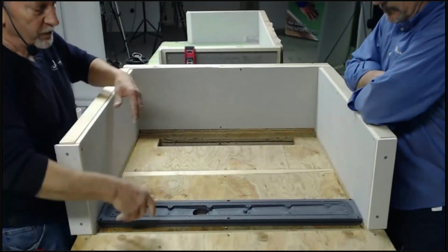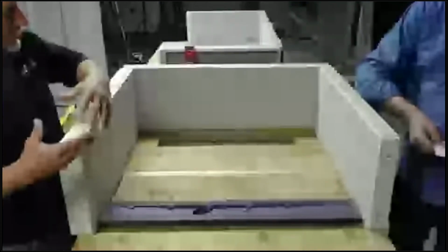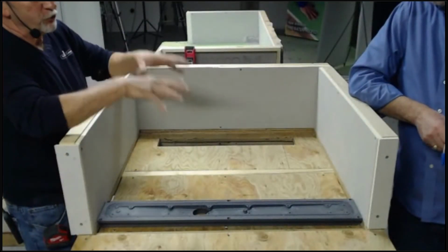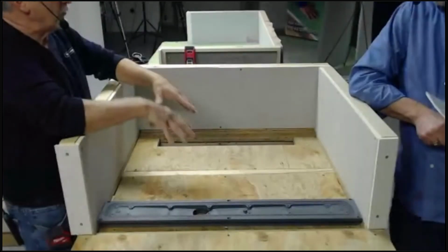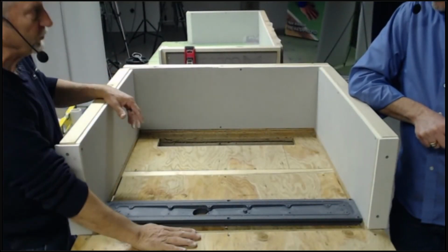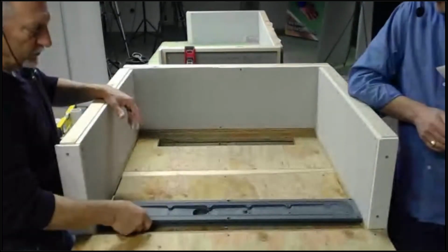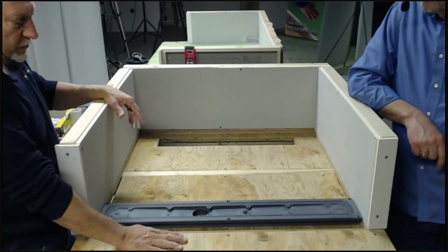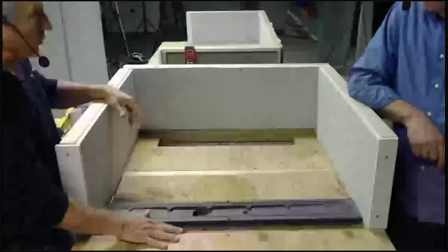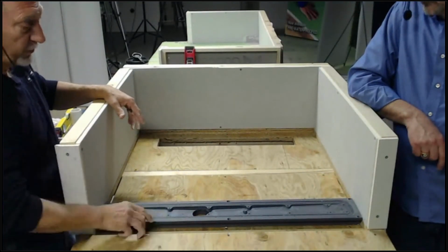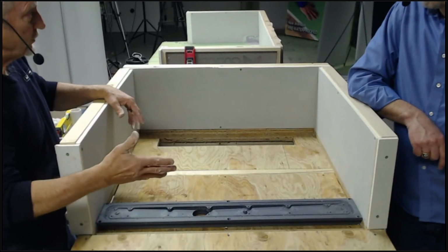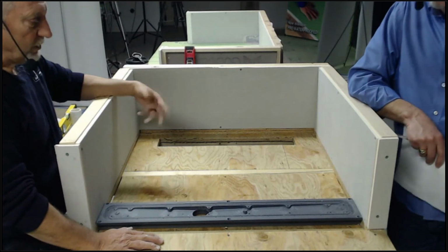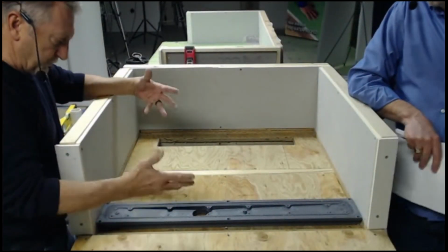Okay, so we talked about, say your floor joists are running perpendicular to the drain. You're not going to be able to drop your drain body down into your substrate, but I still have a 3/4 inch depression. So now that I have a 1 1/4 inch height drain and a 3/4 inch depression, that's going to give me 1/2 inch from my drain body to my dry space. That's easy to work with as far as getting that transition, like you've seen over at the other demonstration. So first of all, I'll place my drain.